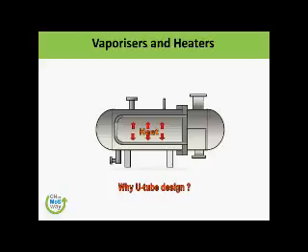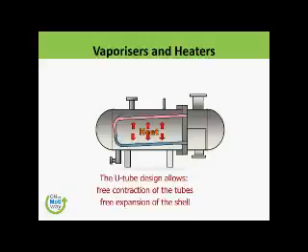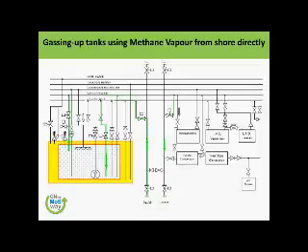This is why we have that kind of flexibility available within this chamber. It will be something like this, where you have your upper tubes very hot, the start of the tube very low, and slowly and gradually. So this U-tube design allows it to expand or contract within the shell, where the steam is coming and going out.